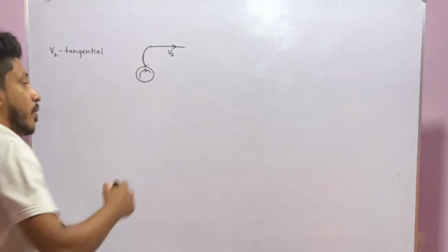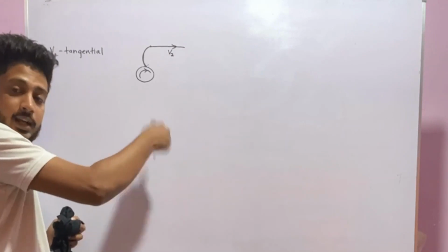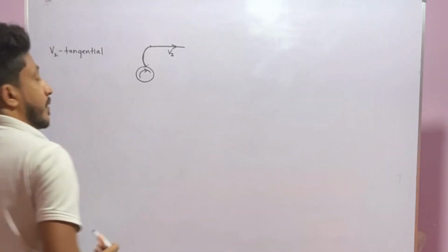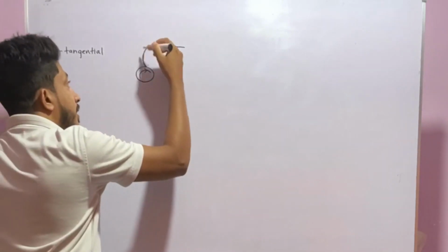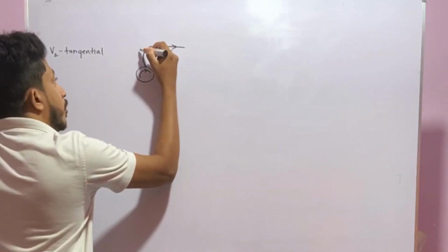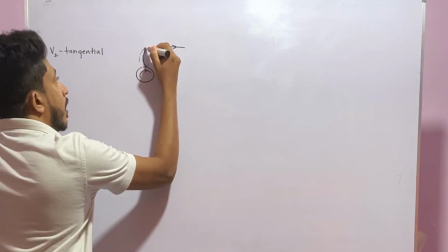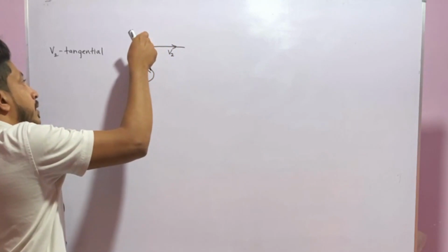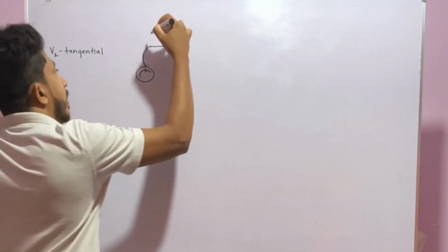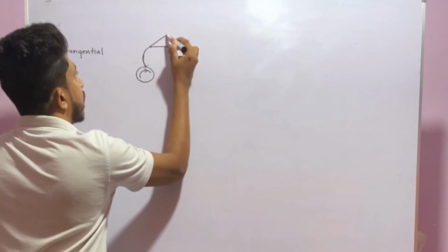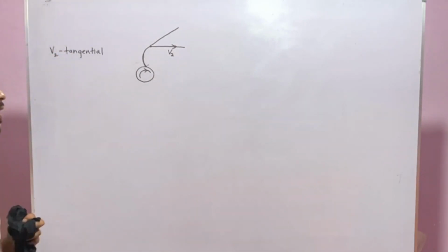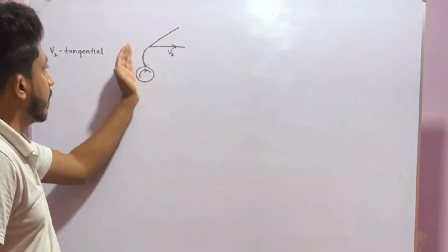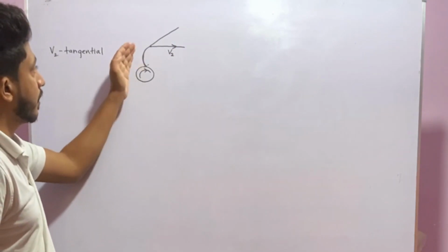And also, you know, when there is something in rotation, it has centrifugal force. Because of that centrifugal force and this curvature, air is trying to move like this. So air has another velocity in this direction. Due to this curvature and the centrifugal force, it is trying to leave the blade impellers in this direction.